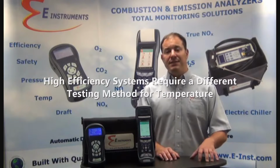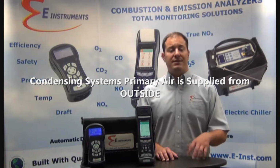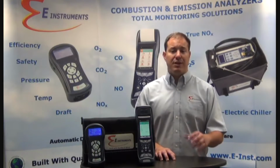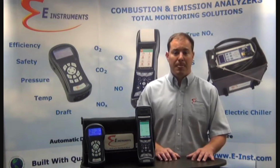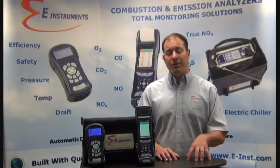Newer high-efficiency condensing furnaces, boilers, and tankless water heaters use a different method of measuring the differential temperature, because condensing systems use outdoor air as the primary temperature, not the ambient room temperature anymore. This is done either by using a two-pipe system or a concentric vent. Both bring in air from outside for combustion. Furthermore, the stack temperatures of condensing systems are much lower than atmospheric systems, more like 100 degrees Fahrenheit, not 300 degrees Fahrenheit anymore. So the importance of properly measuring the correct delta T is much greater for accurate combustion efficiency calculations using your combustion analyzer.